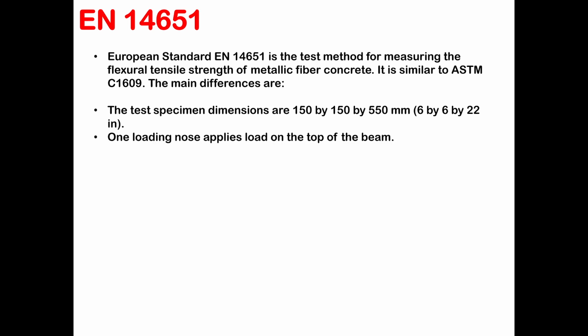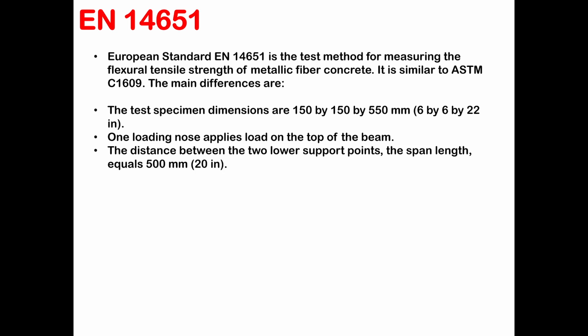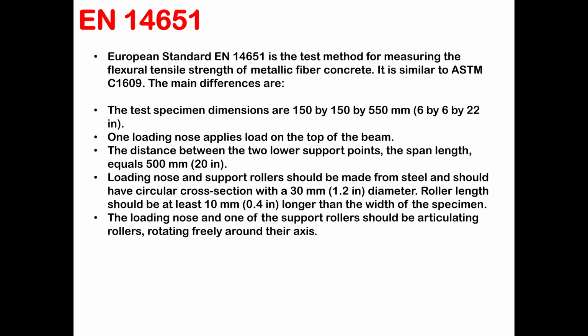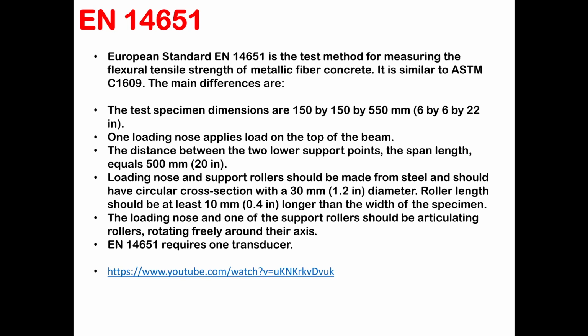The other difference is that it is a 3-point bending instead of a 4-point bending, so one loading nose instead of two. And the distance between supports is going to be different. The loading nose material is going to be different, and the EN test requires just one transducer.